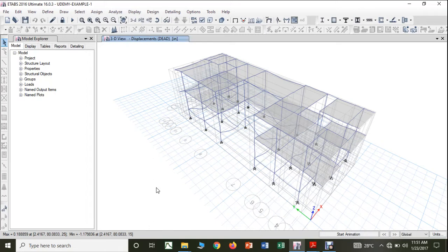Welcome back, learners. As you know, in the previous lecture we were discussing the design of the columns. For the problem that we have considered, we have completely finished the design of the columns. And when we were doing the design of columns, we designed it as a uniaxially loaded column. That means the column will have the axial load and one moment.